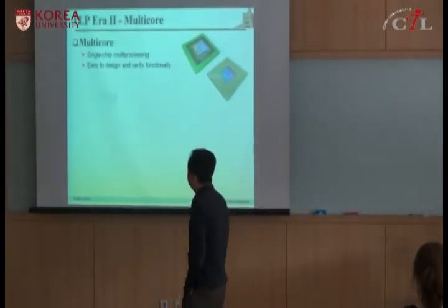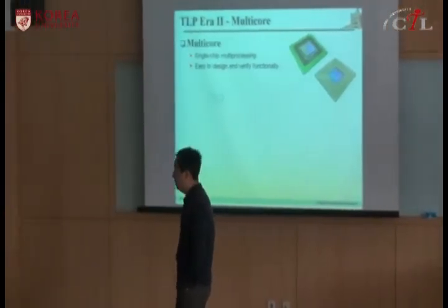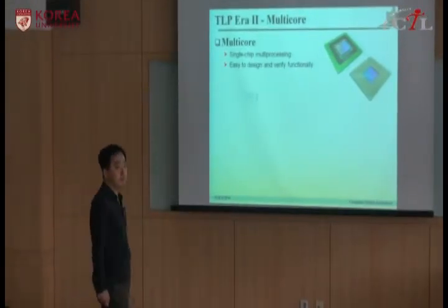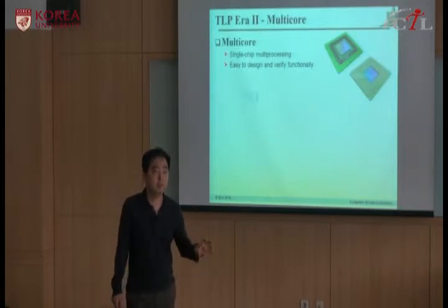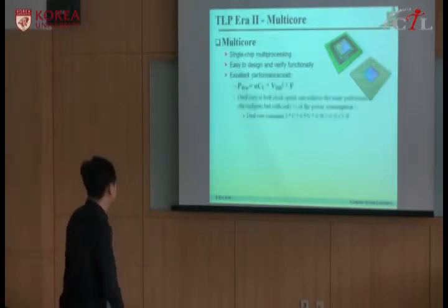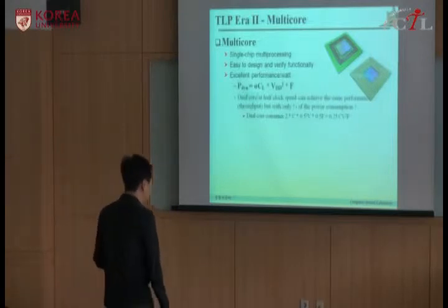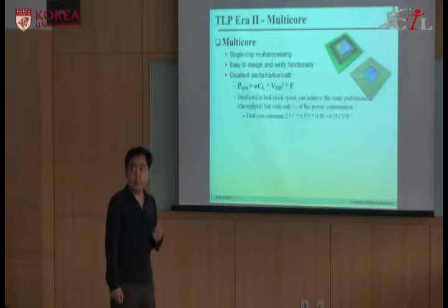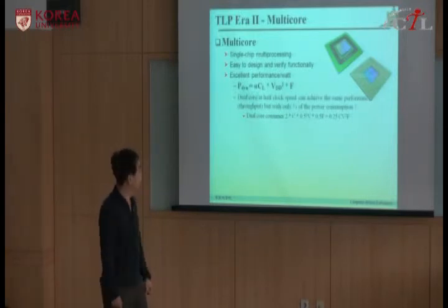So it's single chip multi-processing. The idea is quite simple. It's easy to design and easy to verify functionally. You just have the same core, you can replicate. You can reuse the existing designs. And the other advantage is it actually gives better performance in terms of power consumption.